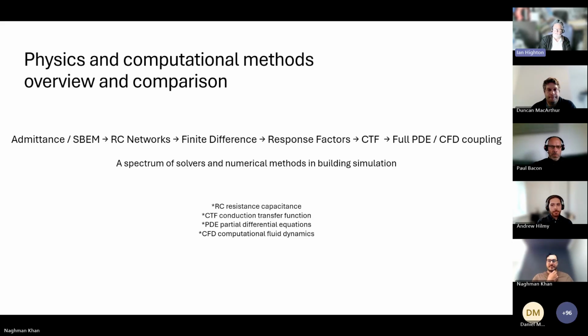Paul, is that about right? Is that a reasonable sort of assessment of what Admittance was doing? Because you're the CIBSE guy. Yeah, exactly that. That's what our design days were, wasn't it? So we did the repeating design day for the summer and the steady state -4 for the winter. It was dynamic in as much as it's a sinusoid, but it was an infinite sinusoid. So you're effectively getting to a kind of steady state based on a simplistic sinusoidal weather pattern. Whereas we found that we get hot patches in the UK, but they don't go on forever, sadly. So that's a pretty massive overassessment.